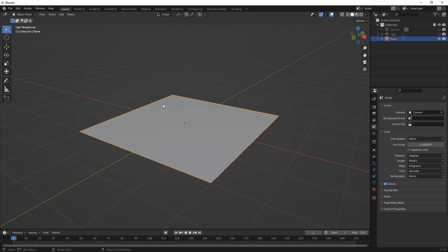Now that we have this plane, we want to select it and we want to begin editing it. So we're going to select Edit Mode. As soon as we do, the entire thing is selected, including the face, the edges, and the vertices. By default, we will be in Vertex Select mode. And again, once we select a group of vertices that creates a completely enclosed plane, it'll automatically show it highlighted in this red color. Now, if we go and we select an individual vertex, you can see that it's starting to highlight the edges and it fades away as it gets close to the next one. This is true as we go around and make our selections.